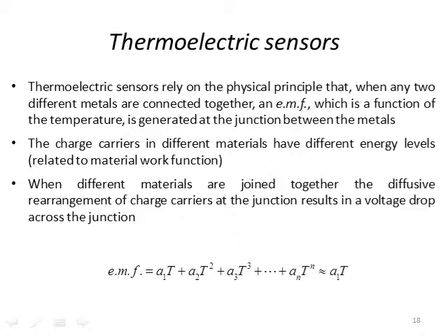So we have these called thermocouples, two materials, well characterized. We solder them together. They create a voltage. That voltage then is a function of temperature. With the right choice of metals, these can be extremely linear functions of temperature and very stable, which is why they're probably the most commonly used sensors in industry, in laboratories, generally inexpensive. You can buy them very cheaply, and they're quite successful.